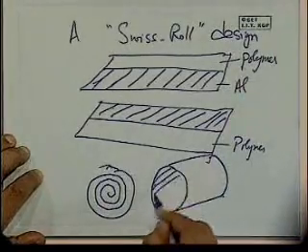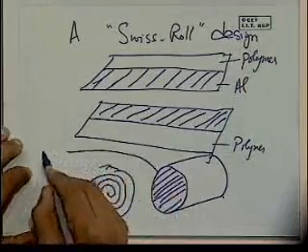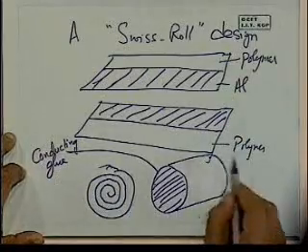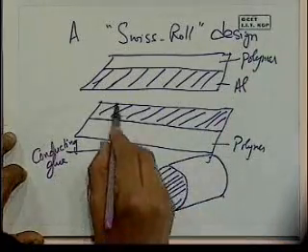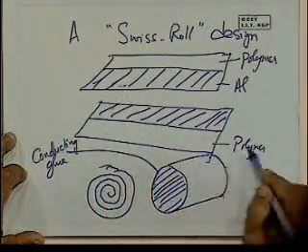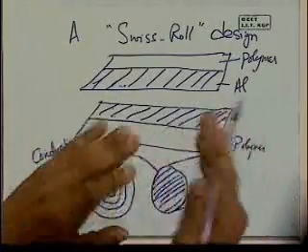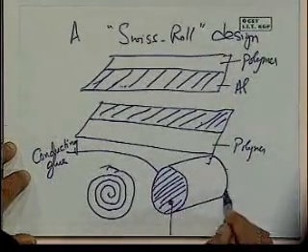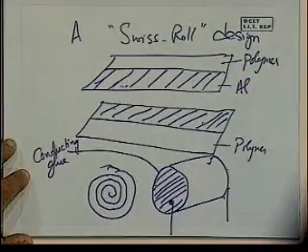Some kind of electrode contact is smeared over the end there. We could have some kind of conducting glue, okay, on both sides. So on this side, it will make contact with, say, this film. And on the other side also, we do the same thing by putting an end contact. It will make contact with this film. So alternate parts of it will get contacted. And then we attach the leads, wires to it on both sides. Do you get it? It's like a little, very compact. It's now rolled up, very much like the ceramic idea there, except now it's so flexible, we can roll it up and get an equivalent capacitor.